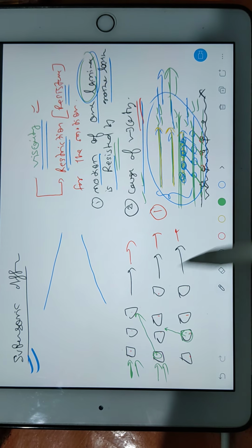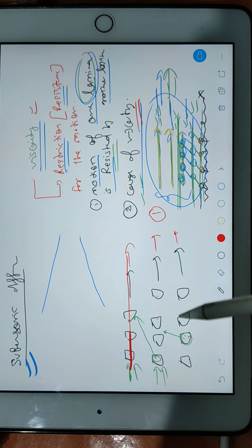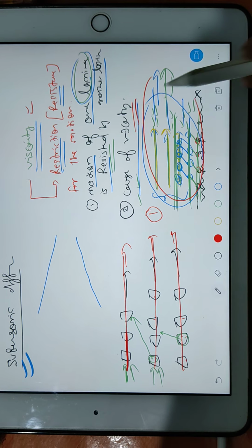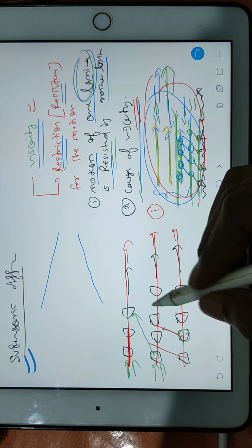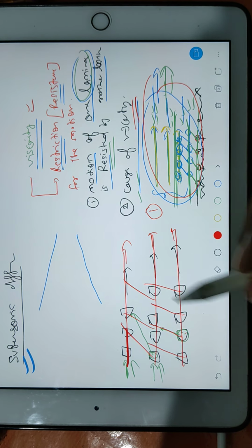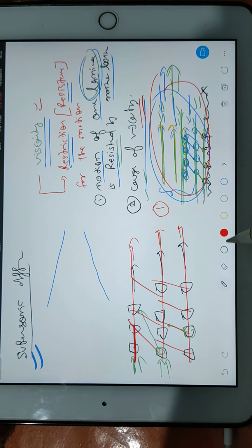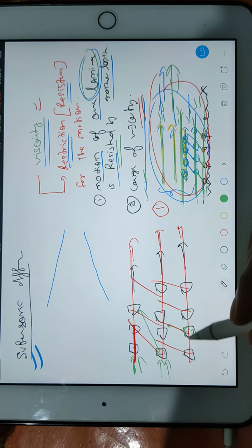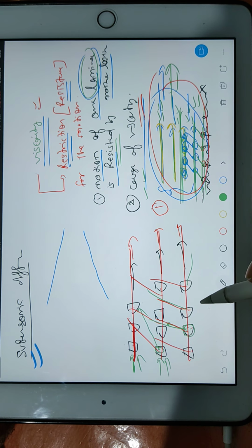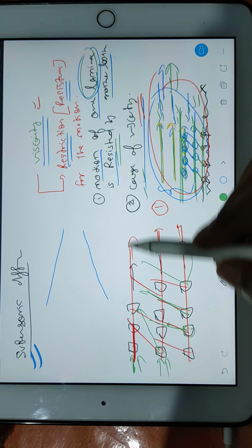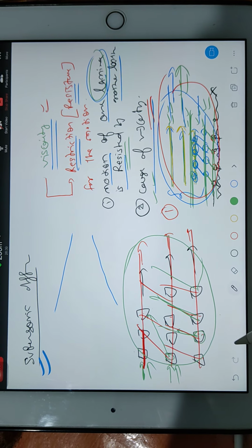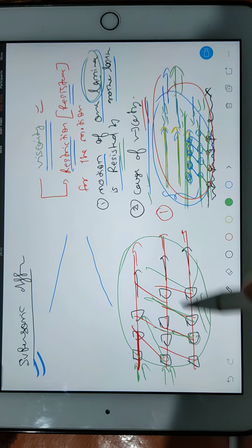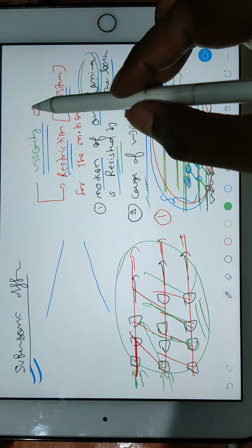This phenomenon: now imagine this total thing is one layer, one lamina. What I explained here is the same thing. This is called mass transfer, or you can also say momentum transfer, right? So this is one more way, because molecules are not stationary. They can go in any random way, so this motion also causes a disturbance to the flow. This is another way which can produce resistance, which can produce viscosity in the liquid.